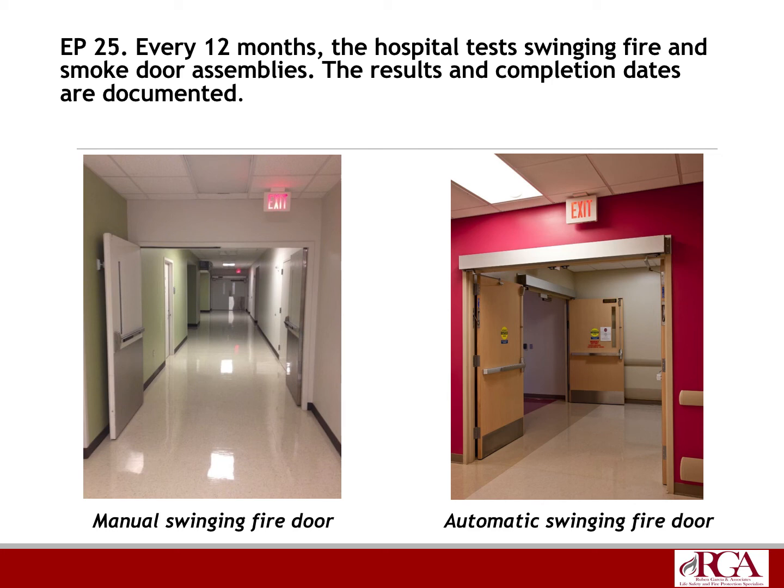My advice is if you're doing them in-house, that's okay too. Make sure they're competent and trained properly. But at least get them checked by an expert the first go around, because you're going to be surprised how many failures you have on your fire doors. Then after that, you can maintain them and get the proper training. And if you choose to do them in-house, then you can if you have those resources. But you definitely want to get these checked from an expert, from a vendor, at least once. And even if you do it in-house, it's good to have an expert come out every so often to validate that they're being checked properly.